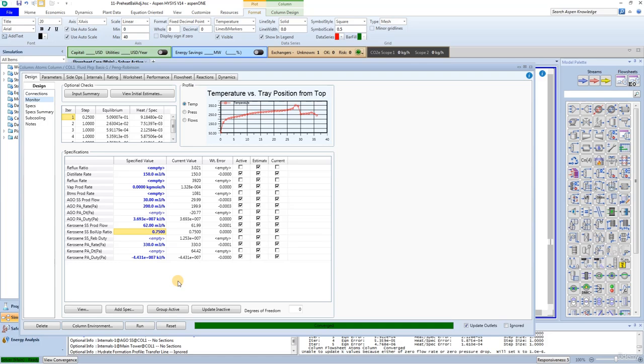Task 3. Adjust column operating conditions. To model this atmospheric crude column, you utilized a reflux absorber template. This reflux absorber doesn't have a reboiler of any kind associated with it. However, a side exchanger that introduces some heating duty can be simulated near the bottom of the column by attaching an energy stream. This attached energy stream represents an additional degree of freedom for the system and would thus need to be defined or calculated via some other specification.